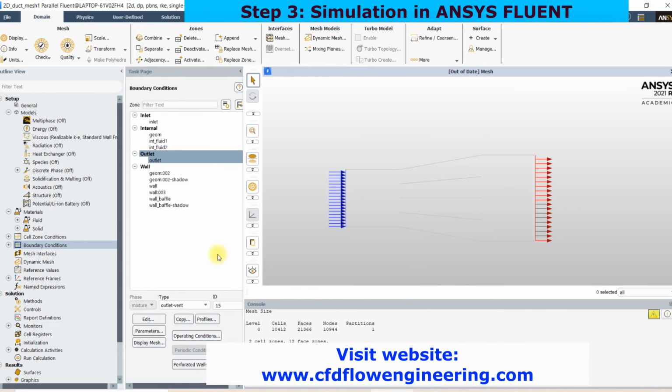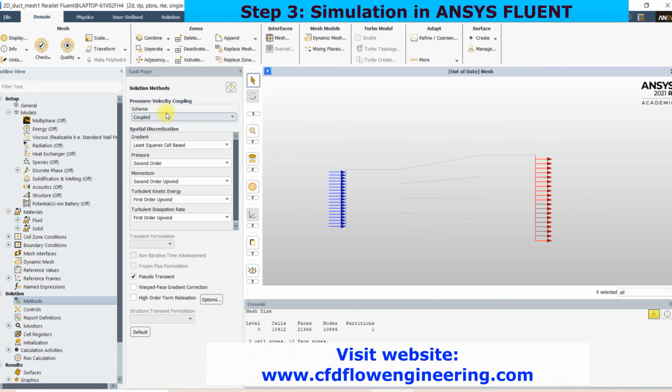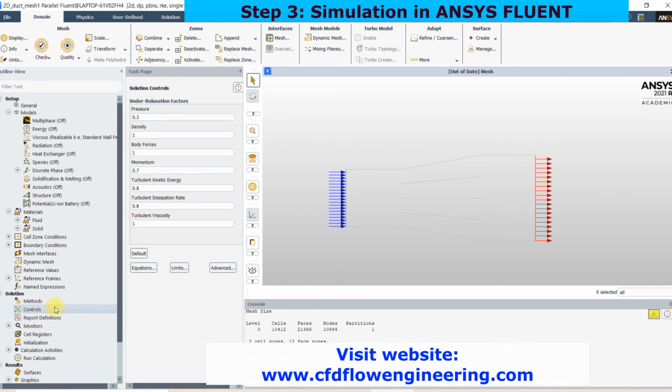And then control. I take the SIMPLE solver. You can change the relaxation factor if you know the simulation well, for faster convergence.